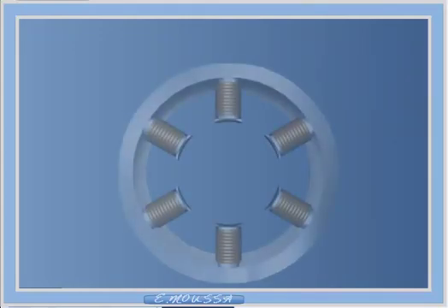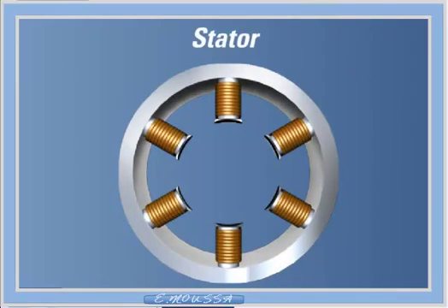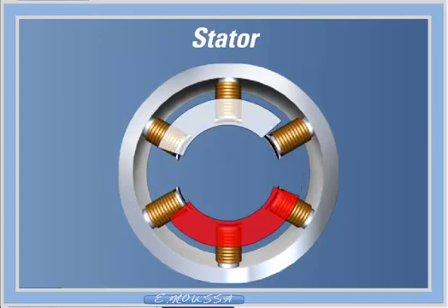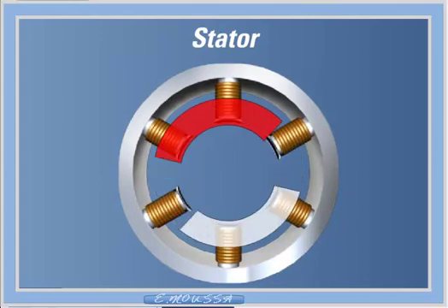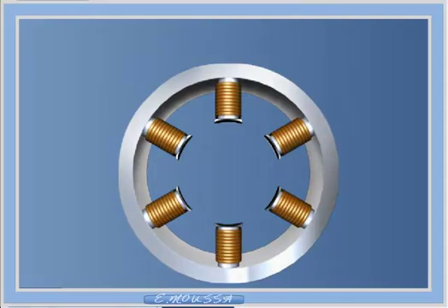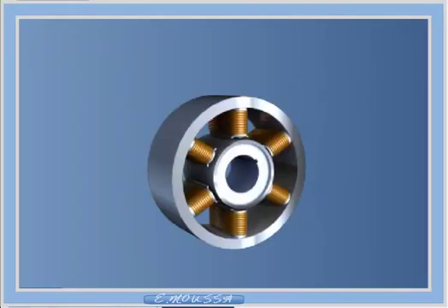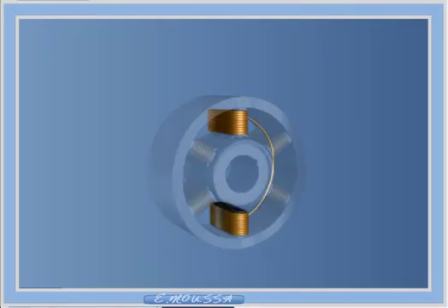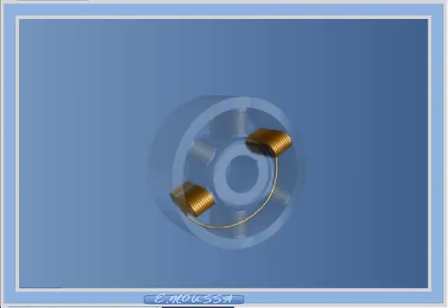The stator of an AC motor consists of a hollow cylinder with electromagnets forming the walls of the cylinder. These electromagnets remain stationary. The rotating field that they form when current is applied is referred to as the stator field. An illustration of how 6 electromagnets are wired and oriented to create the stator of a two-pole AC motor is shown in this wiring diagram.